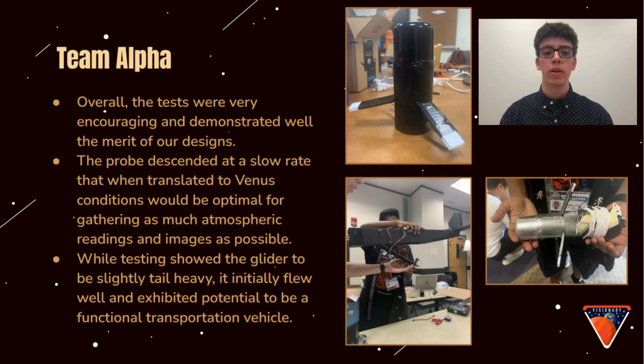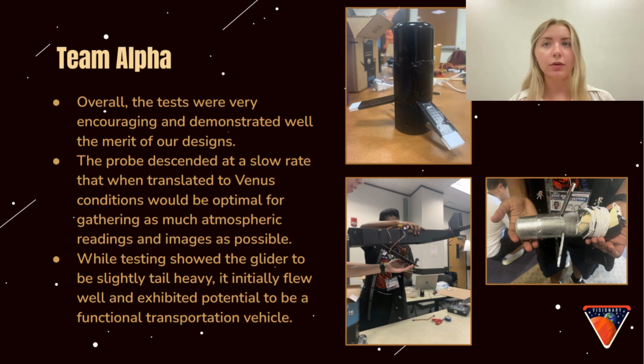As for the powered glider, our team held various tests in an open field to test the stability and aerodynamic properties of our plane. We found that the control surface mechanism and ejectable hatch design were proven to be effective. We also made sure to focus on leveled and stabilized front wings, and that all wires and sensors inside the fuselage were connected for correct movement and a safe flight. Overall, the glider achieved acceptable success through a meticulously engineered and aerodynamically optimized design.